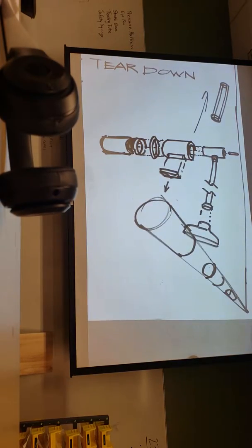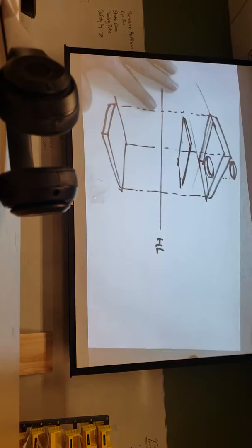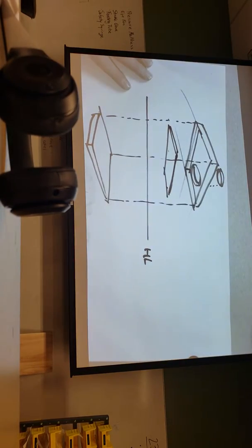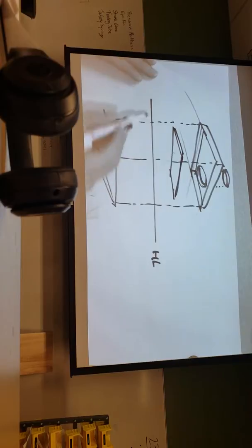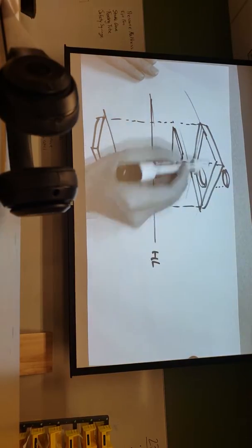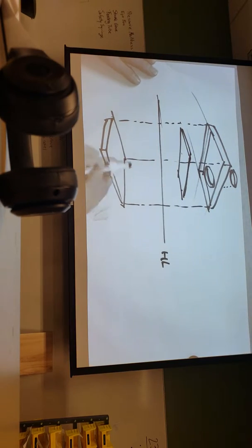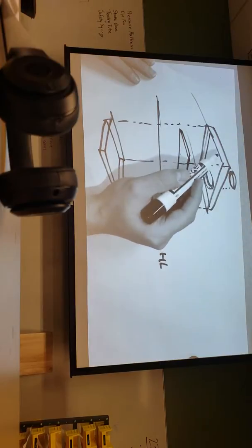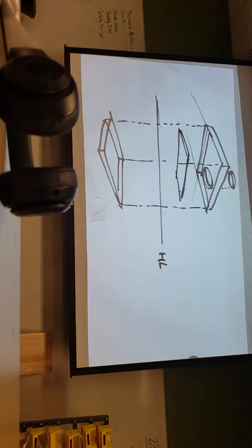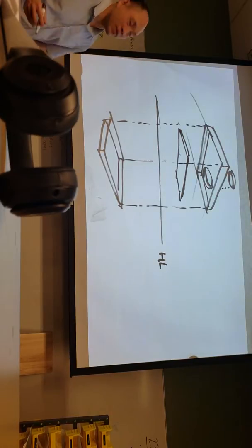But you can also draw your exploded views such that, especially with the vertical stack, you can go across the horizon line so that anything above it you start to see the underside of, and anything below you start to see the top of. This is helpful if you have detail that's both underneath and on top of components. So you can also draw it this way. I don't see students do this as much, but it's also a more descriptive view.